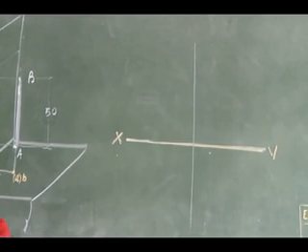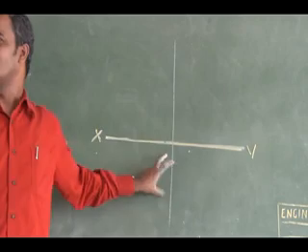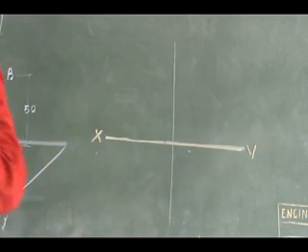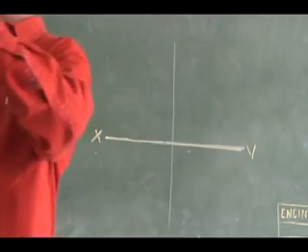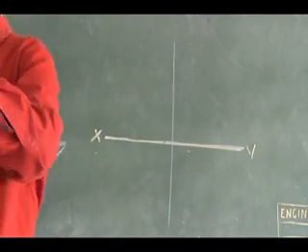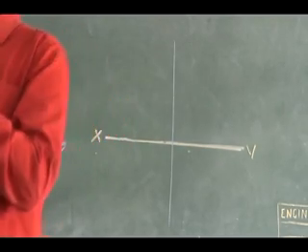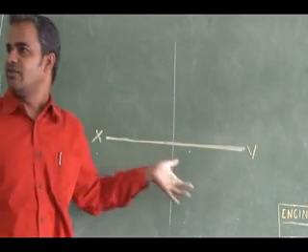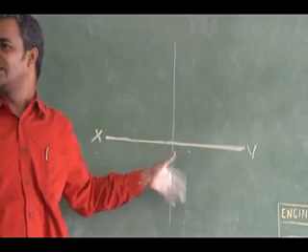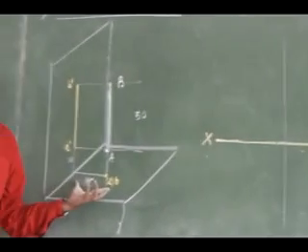This is the first angle projection, you know. The above distance you have to mark above the reference line. In front of distance you have to mark below the reference line. There will be only two data given for the position of the end, that is an above data and an in front of data. Above data is 10 mm. In front of data is 15 mm.